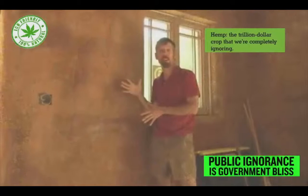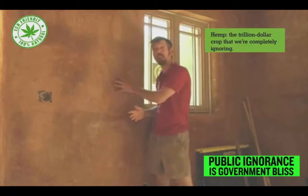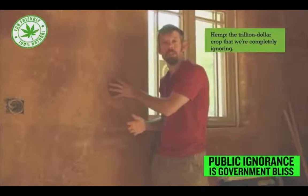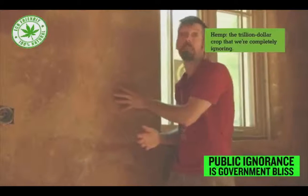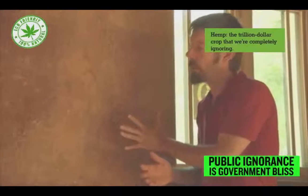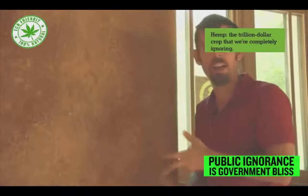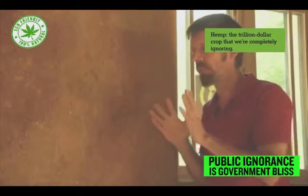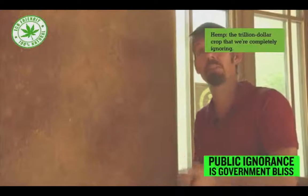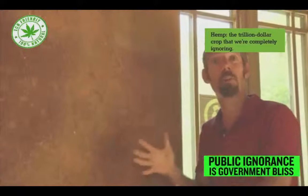Now we're on the inside of the building. We were talking about the breathable qualities of hempcrete. This is a hempcrete wall with a scratch coat of earth plaster. This is actually a plaster that we made on site with just clay, subsoil, and sand we mixed together. This is another great quality of a hempcrete wall, that we're able to plaster directly onto it without plywoods, drywalls, laths, drainage planes. It's simply the material itself, the insulation itself can be plastered. That saves us a lot of steps, a lot of time and money. And also it allows us to create this breathable wall I was talking about.